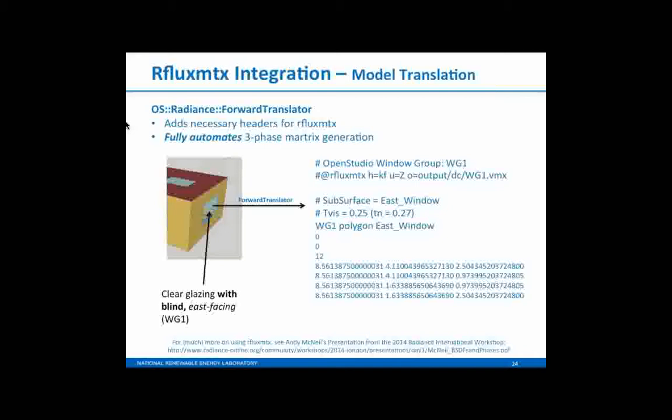And Andy McNeil showed a couple screenshots of some lighting manufacturers' websites where any lighting designer today is not being unreasonable to think, well, I want to use XYZ, Zumtobel's XYZ light fixture. They know they can go to Zumtobel's website, look up that catalog number and pull down an IES file, which is basically the same exact thing as a BSDF, but for that specific distribution. It's a much simpler problem.